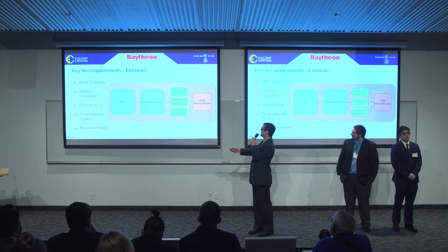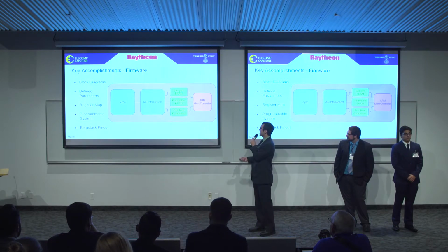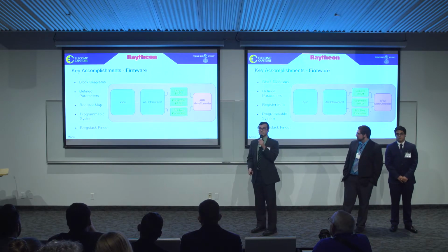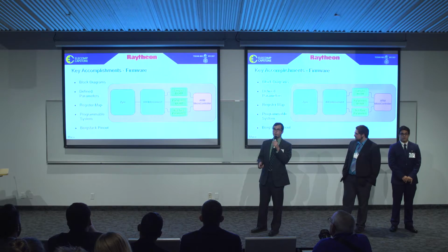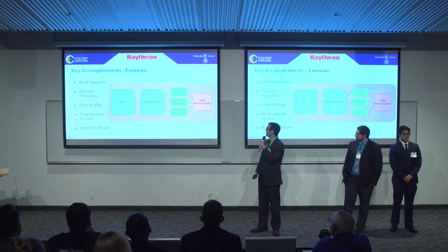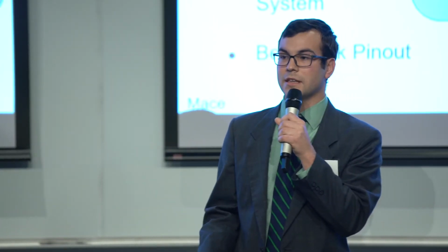The programmable system has our Zynq chip, which controls the master clock, reset, GPIOs, DDR, and fixed IOs. The other key feature is our 3 dual-port BRAMs, each servicing a different portion of our project. The reason we chose dual-port BRAMs was so that as the Zynq writes to the BRAMs, the ARM processor can simultaneously read. I then created a separate project within Vivado where I did the Berg stack pinout. Here I took all the signals traveling from software to the PCB and placed them based on voltage and drive strength. After this was complete, I was able to export a constraints file for the FPGA, as well as a spreadsheet for the Berg stack pinout, which will aid Jose in his PCB design.